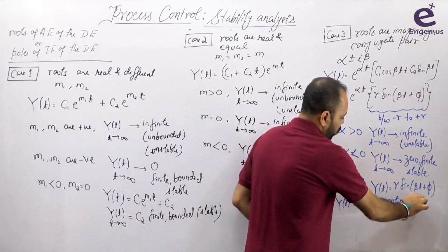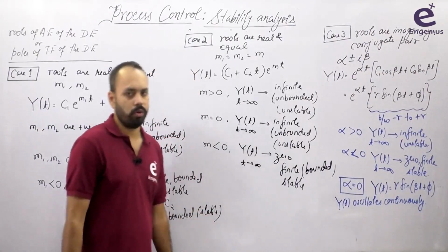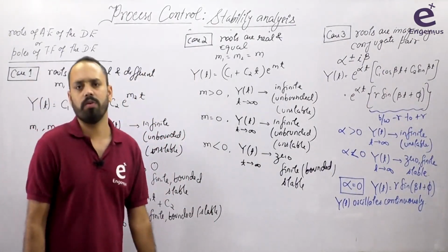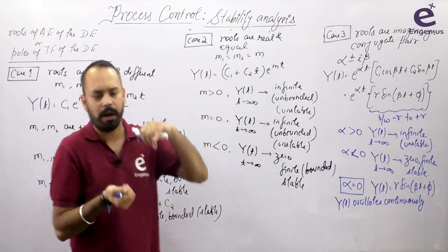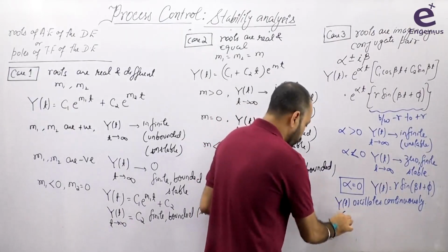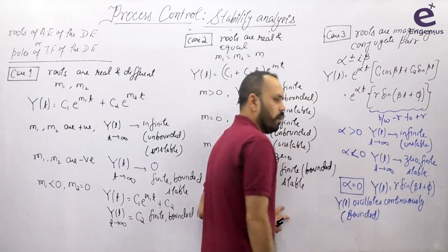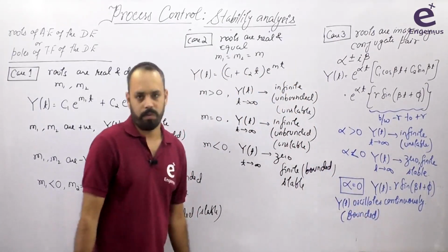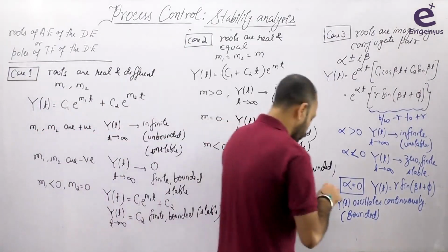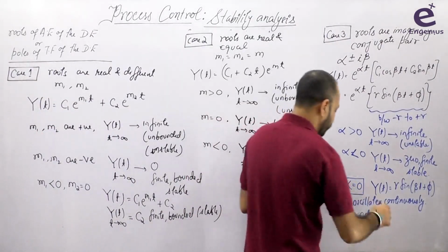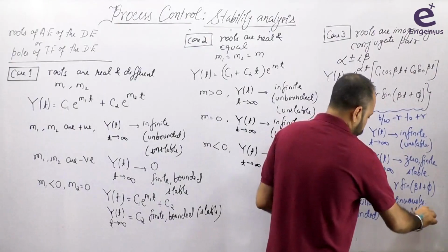Yt oscillates continuously. So आप इसको bounded बोलोगे या unbounded बोलोगे? Of course it is bounded. There is no doubt. Because it is continuous oscillations are always in a maximum and minimum limit. So it should always be called as bounded. तो बोलेंगे तो bounded, there is no doubt. But I should call it stable or unstable. That is the problem. I should not call it stable. I should not call it unstable. So here, please note that I will use a word which is called critically stable.